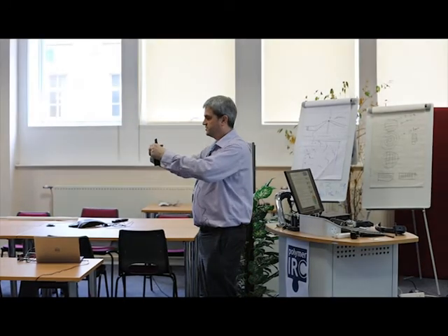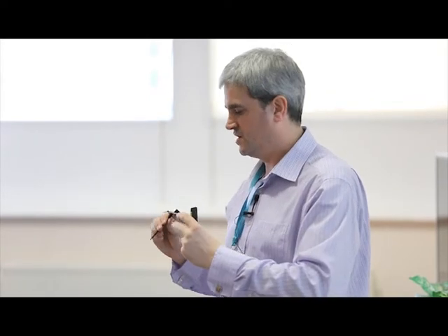part. It's a test specimen here, but you can see this is the sprue, so the nozzle tip will end here. This is the sprue that takes it into the mould. The mould splits down the split plane here. And you might be able to see little circles on the back of the part that indicate the location of the ejector pins. We have an array of pins that pushes the part out of the mould once the cycle is complete. So it's an effective way of removing it.